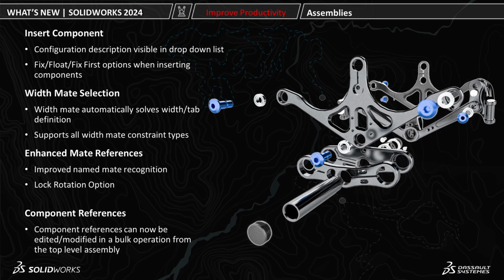In review, in SOLIDWORKS 2024 for Assemblies, we have new capabilities in the Insert Component command, including the ability to see configuration description and define the fix/float behavior when inserting components. We also have improvement to the Width mate selection where it automatically defines your Width tab definition. With enhancements to mate references, we have improved named mate recognition and the ability to lock rotation with our mate references. Our component references can now be edited in bulk operation from the top level of an assembly.